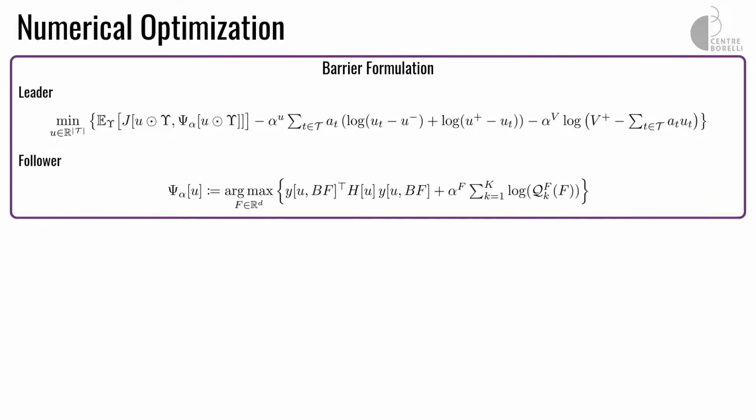Okay. And maybe one last question: in the argmax expression, why is it natural to have h of u instead of just identity? My understanding is that with this term, you're saying that it's much worse to have displacements in the parts which are supposed to be stiff. Whereas if you had dropped the h of u, the model could cheat and say that this point can move because it's not stiff anyway.